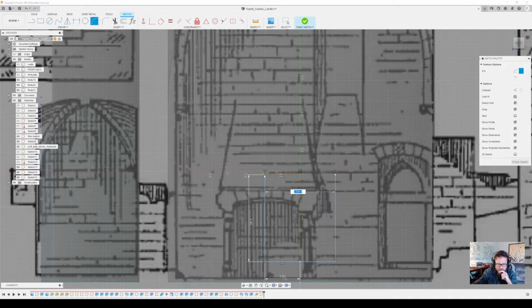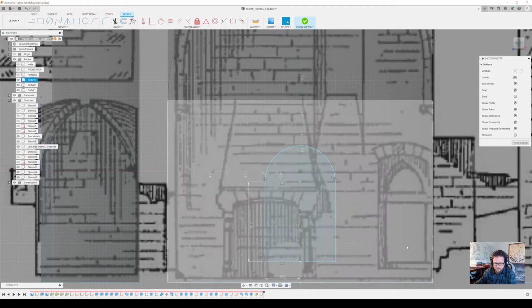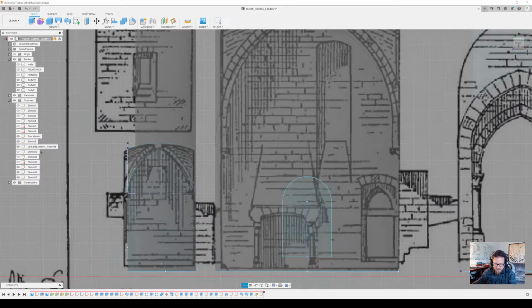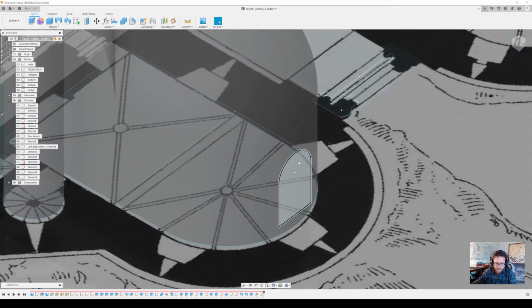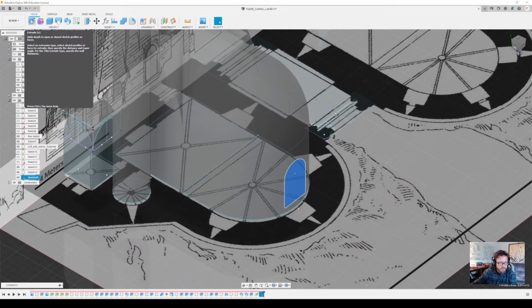And let's go 1, 2, and that's a little bit higher than I really wanted this to be, but that's okay since I have this defined length. I'm just going to shorten it, say 2.2, and that'll lower it. I mean, this is not super important. Since you don't have anything to trace here, we're just going to follow what's going on with the height of this. I'll hit finish sketch there. All right. Again, we want to make sure that we are extruding out without merging in this case.